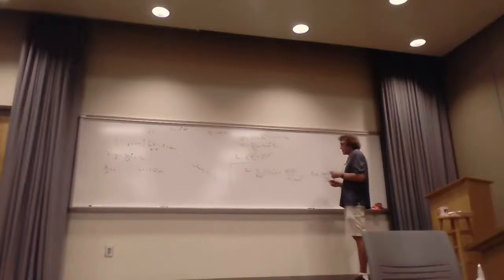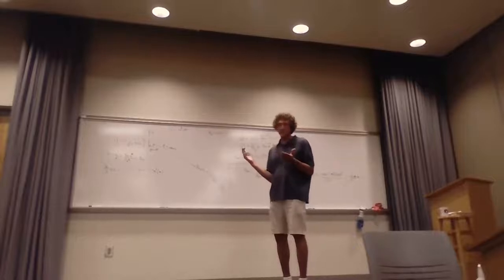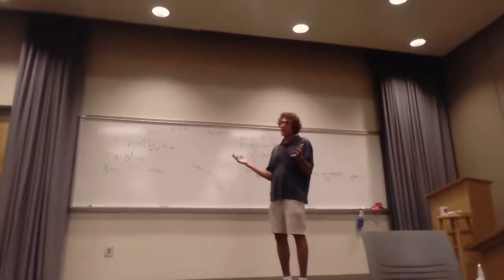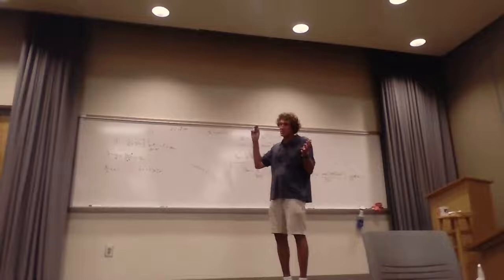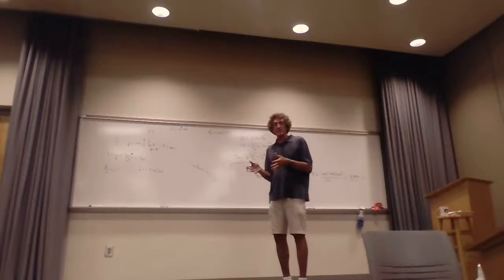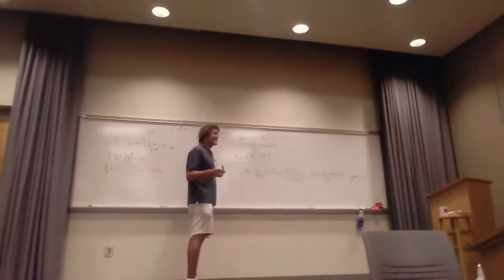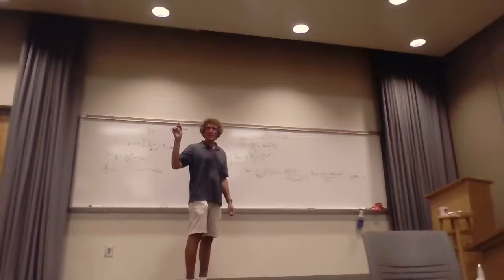So that's total power. And again, just doing it in inverse, but there's many ways to get this. You could get the electric field from a short dipole, j eta beta I L over 4 pi R times the sine of theta, and you could get I from that, and I put the radiation resistance there, right? So it doesn't matter which way you use, you could use that as a confirmation method just to make sure you got the right value. Once you have the total power transfer, I think they wanted I, right?